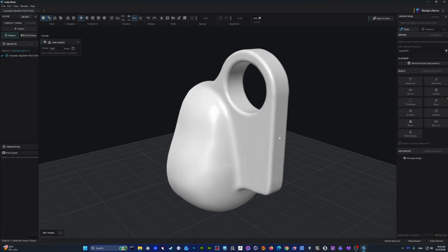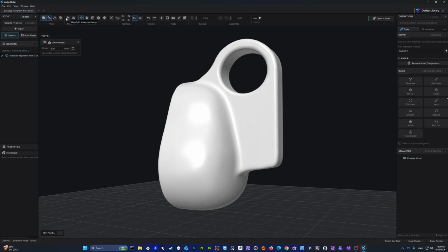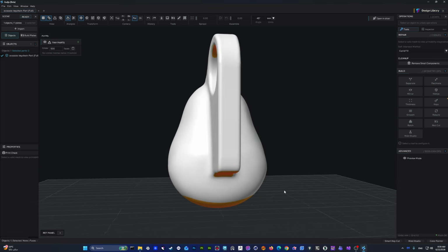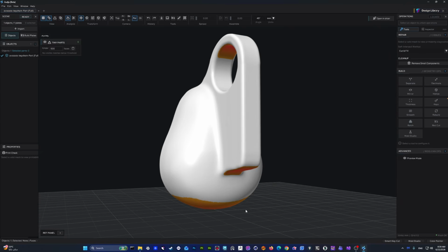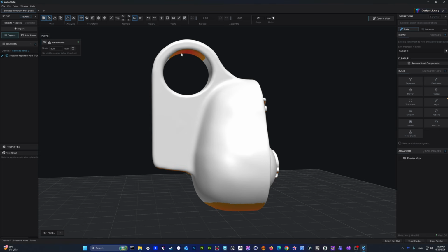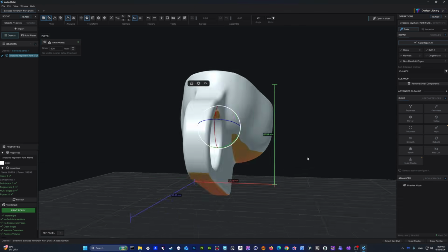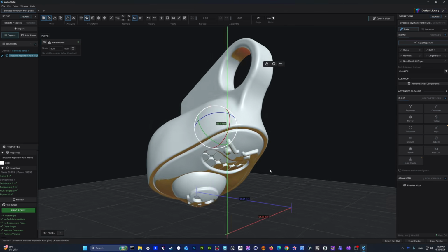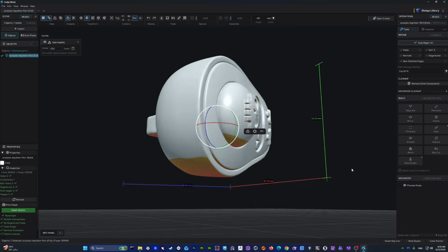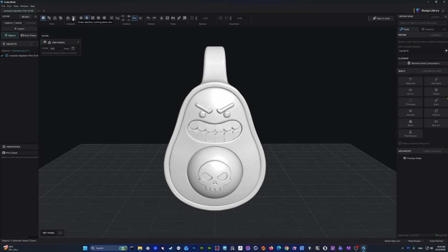If you want to see where the overhang is before you do manual support in the slicer, if you go here, that's the overhang of the model. So you must add support here and here, and one from up to here. As you rotate the model, it's gonna reflect what you're gonna do, as you can see. See? All right.